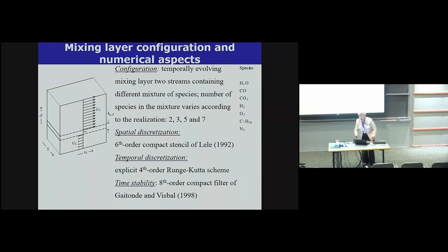So what we do is we put in the layer initially 4 vortices, we perturb, and we let the simulation go from a laminar to a turbulent state, a state with turbulent characteristics. How do we know that it is a state with turbulent characteristics? We compute the spectra. They're smooth. They drop like a stone at the high wave number end, meaning that everything is very well resolved, okay?